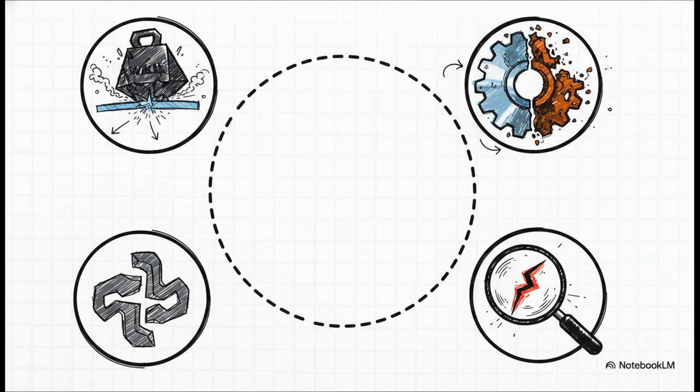You've got to evaluate the extent of localized stresses, how certain you are about the exact mode of failure, and how many simplifying mathematical assumptions you made back in step 3. The higher the uncertainty in literally any of these areas, the higher your factor of safety must be. Bumping up that factor ensures that even in the absolute worst-case scenario, the machine remains reliable and, most importantly, safe.